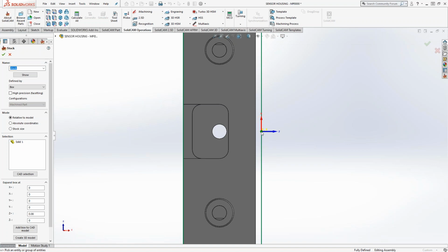So we get you to do it first, only because sometimes you don't have something that represents that stock. But knowing that you will put in this much material, or maybe even knowing that later on you will add a 3D model, you have the ability to do some shifts of your coordinate system for the eventual definition of your stock, whether it be a 3D model or this box definition here. Now, with that, got some questions. What is the advantage of choosing top center?